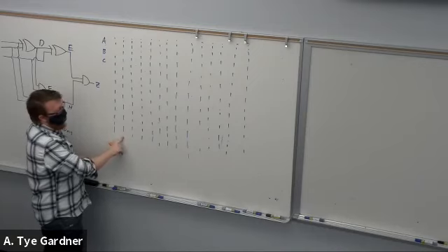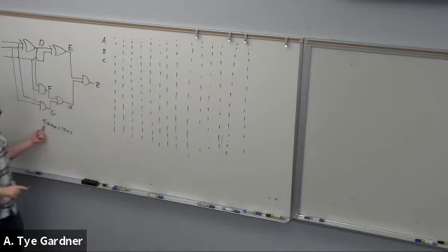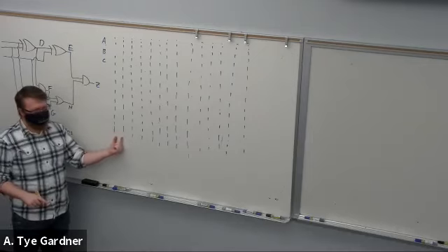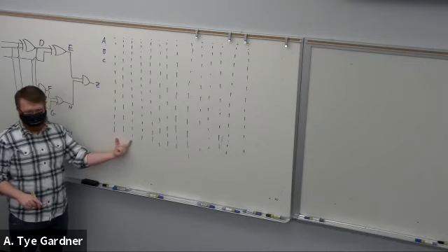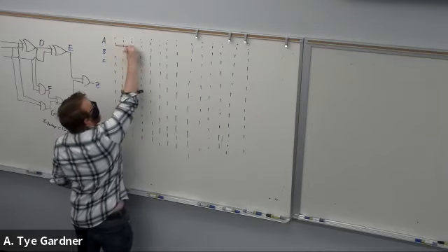And I don't want to deal with too crazy of propagation delay problems, because the propagation delay limits our ability to, well, it limits the speed of the circuit. If we go too fast relative to this time delay, we're going to have issues. So I'm going to use 10 nanosecond windows, but I'm going to do 20 nanosecond bit changes. So I'm going to be 0 for 2 on the first one.